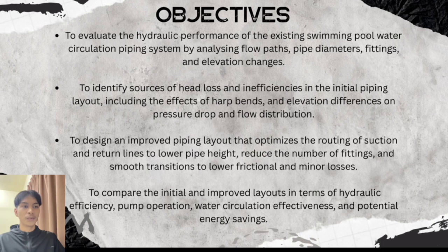The second objective is to design an improved piping layout that optimizes the routing of suction and return lines to lower pipe head, reduce the number of fittings, and smooth transitions to lower frictional and minor loss. And the last one is to compare the initial and improved layouts in terms of hydraulic efficiency, pump operation, water circulation effectiveness, and potential energy saving.